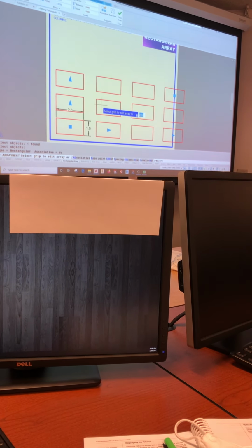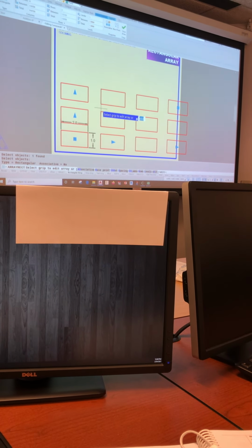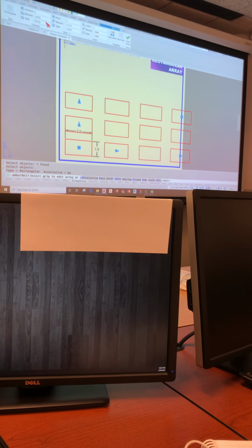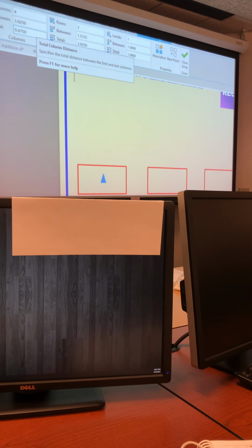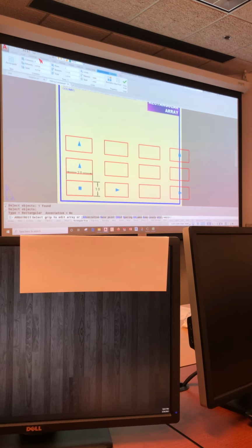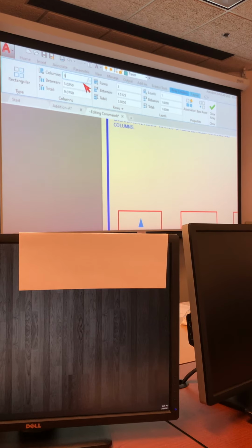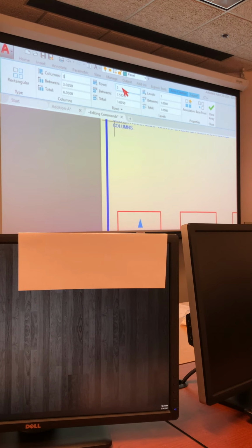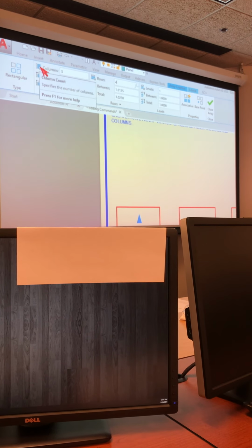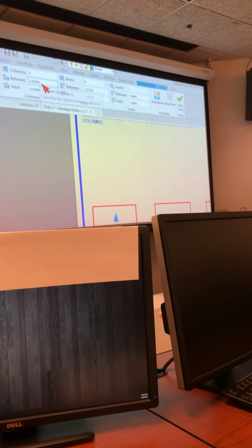of just a random, like 3x4 array. Okay. There's several ways to adjust the array. You could use the blue arrows or the blue grips, or you could set this up on the ribbon. So up here on your ribbon, you'll see, well, let me get this zoomed in so I can edit. So here I can say I want 3 columns, 4 rows, and you'll notice you get a preview. Columns are vertical, rows are horizontal. Some days at 5 o'clock I don't know the difference.